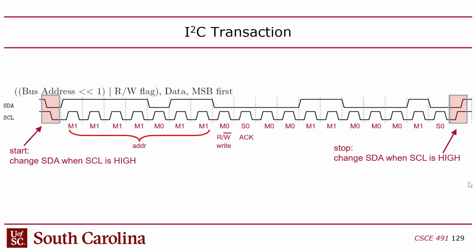Now, I2C is always most significant bit first for the address and the data. I think with SPI it can be either one, depending on what peripheral you're talking to. On the Atmel 328P, I think that's a configuration bit for the SPI: most significant bit first, or least significant bit first. But with I2C, this is standardized.